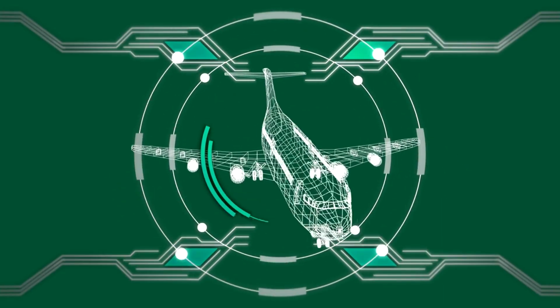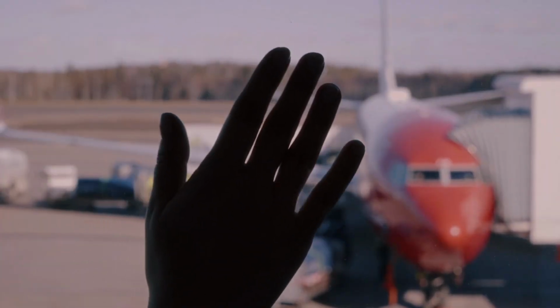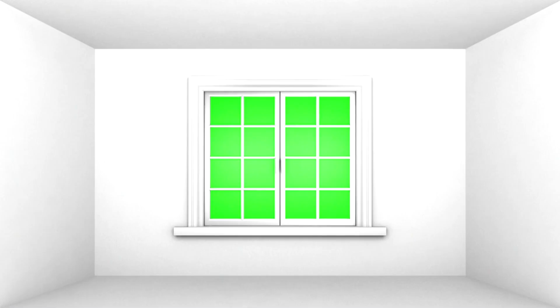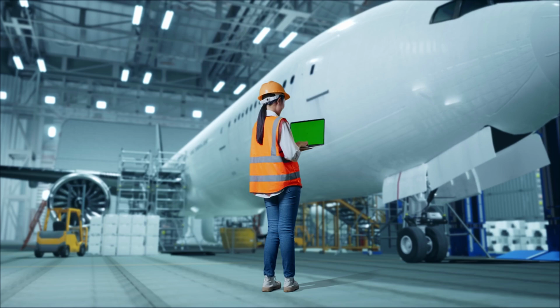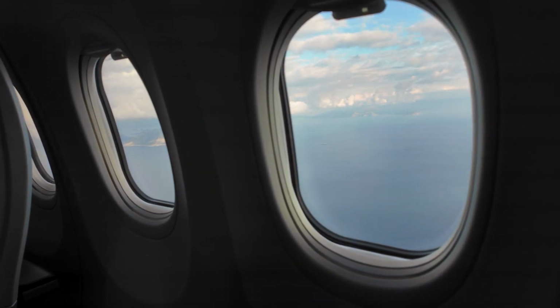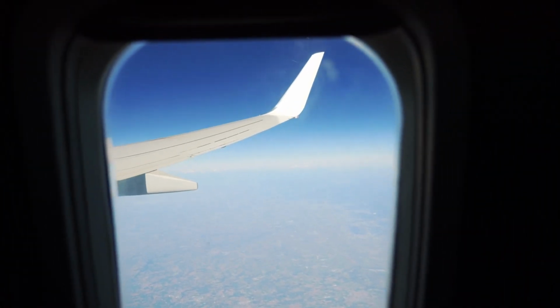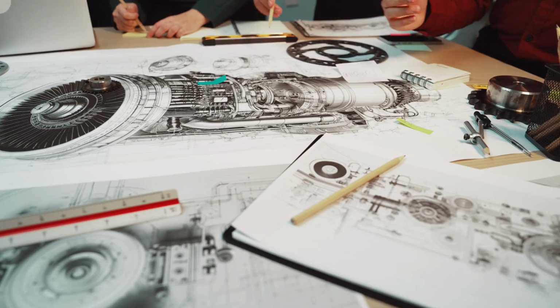Rounded shapes distribute pressure much more evenly across the structure. Without sharp corners, stress cannot build up in a single point. Instead, it spreads smoothly around the edges of the window. This dramatically reduces the risk of cracks forming in the aircraft's fuselage. That is why modern airplanes always use oval or rounded windows. The shape helps maintain the structural strength of the aircraft even after thousands of flights.